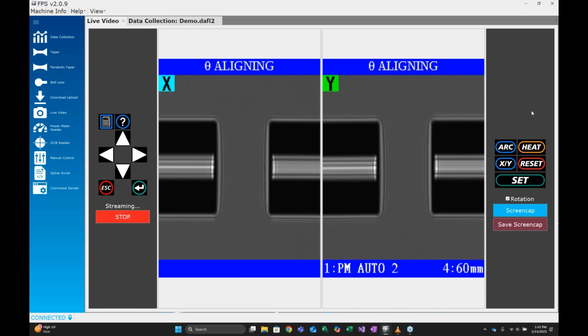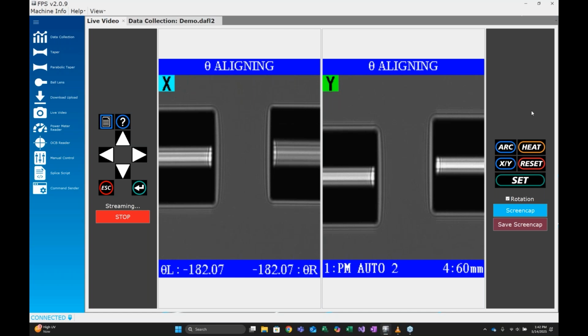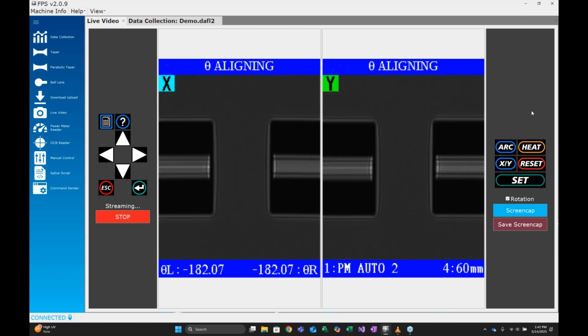Now, what you'll see here is what the splicer will do is you'll see it taking steps, right? And the reason for this is because I told the splicer I have the coating of the fiber sitting in the V groove, right? If the coating of the fiber is sitting in the V grooves, what will happen is a lot of times the friction coefficient between the acrylate coating or whatever coating it is, most of the time it's acrylate, and the ceramic V groove is pretty high, right? Especially when it's captured by that clamping pressure from the clamp above, right?